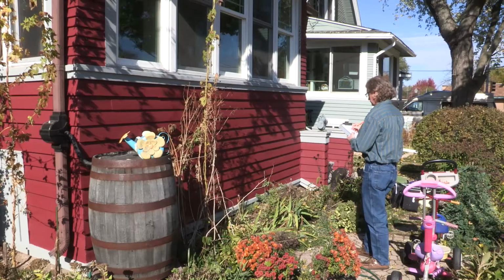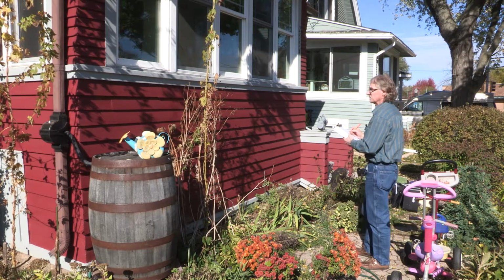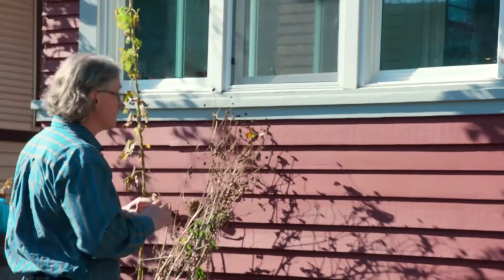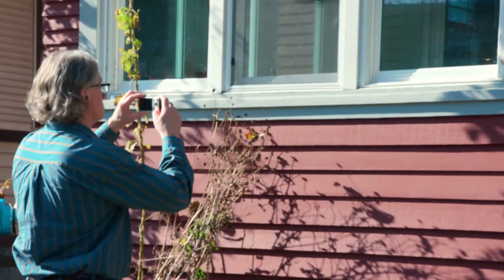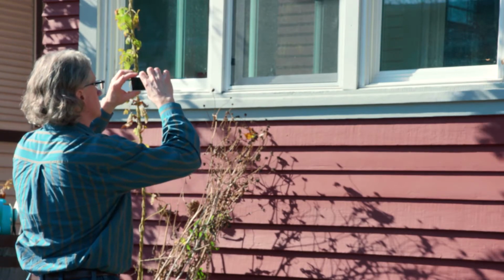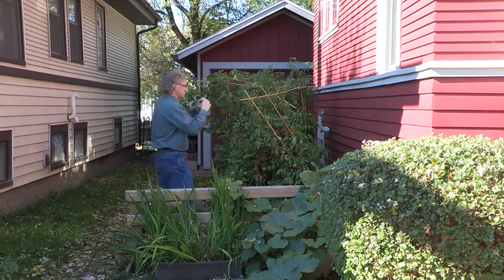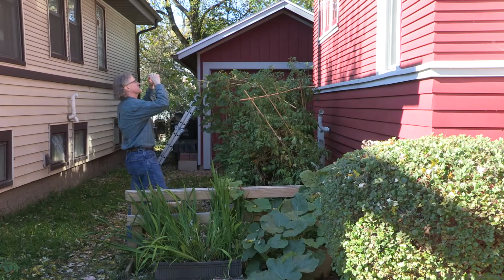Look for areas of bare soil, especially where there is evidence that children play or might play in the area. At the same time, take note of any areas of deteriorated paint that will have to be tested later. It is a good idea to take pictures of all four sides of the exterior of the house. These can be helpful to review the actual number and location of windows and roof lines.